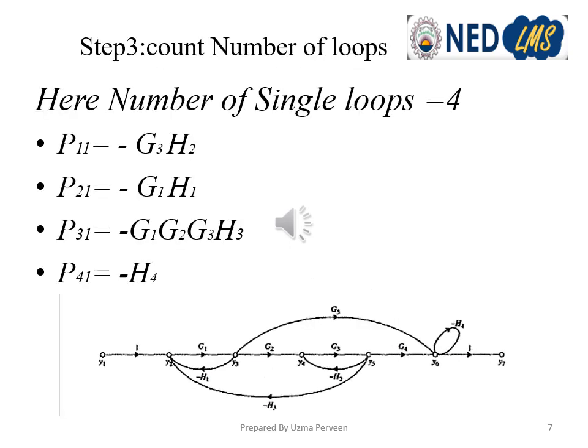del. Now in the formula of P1 del 1 plus P2 del 2 upon del, we have already calculated P1, P2, which is the forward path. Now we have to calculate del, and to calculate del, first we have to see how many loops are present.